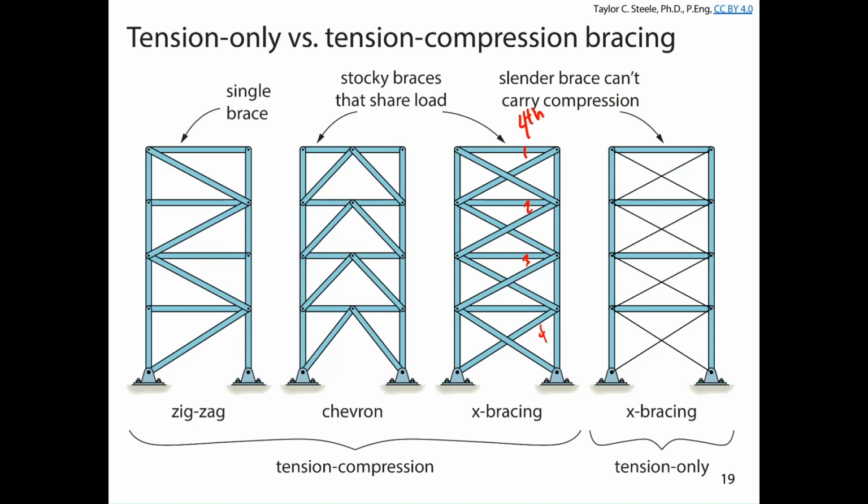So let's look here. If I was to draw a section through that truss, I'm going to have a member in tension, a member in compression, and I'll ignore the columns for now. Is there any reason to think that the force in this member is going to be significantly different from the force in this member? They're the same length, they're the same section size. Wouldn't they be somewhat similar? Might not be exactly the same.